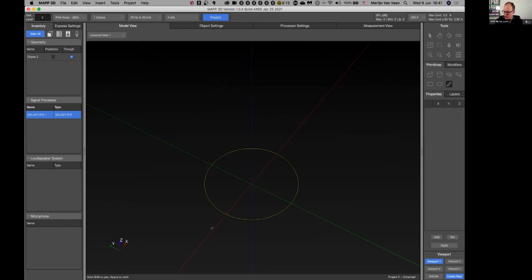And I'm first going to change this into a hemisphere rather than a circle. So I'm going to draw a line, and that line will consist of 2 points. And I'm going to make those points exactly be the bisector of my circle. So I'm going to massage their x, y, and z coordinates. I'm going to hit apply. That now becomes a perfect bisector.